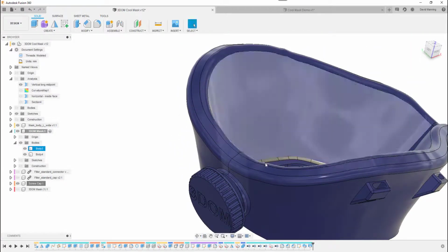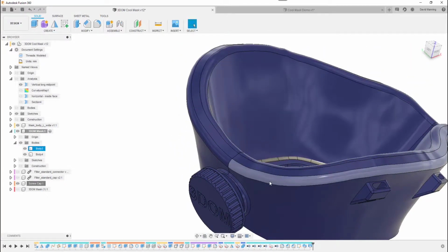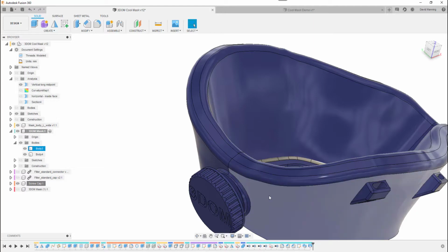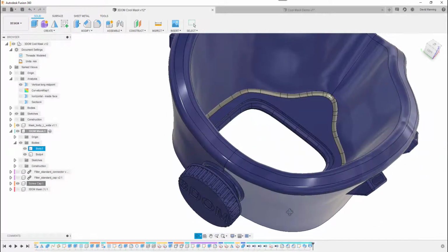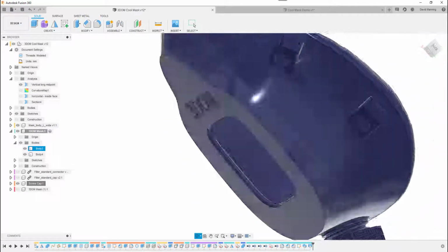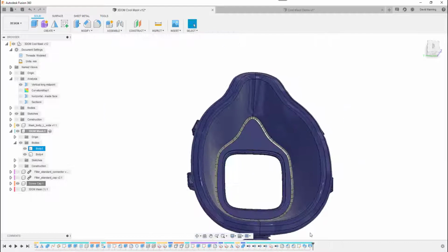Water would be interesting because it'll expand once it's frozen, so freezing it might not be the best idea, because if you filled it up that would expand and you'd probably fatigue and potentially break the print. One option might be to print that in flexible. I'd be really interested to see that if anybody does it.